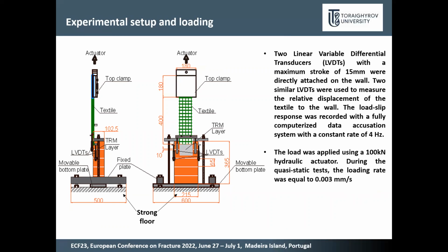The load-slip response was recorded with a fully computerized data acquisition system with a constant rate of 4 Hz. The load was applied using a 100 kN hydraulic actuator, and the loading rate was equal to 0.3 millimeter per second.